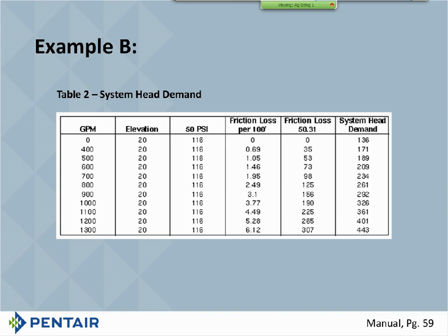And if you look, you can see those numbers are pretty similar to what we saw before, only we're doubling our flow. So of course, what we see here is that at zero flow, the system is the same. Whether it's 8-inch pipe or 6-inch pipe has no effect on that system if there's no water flowing through it.